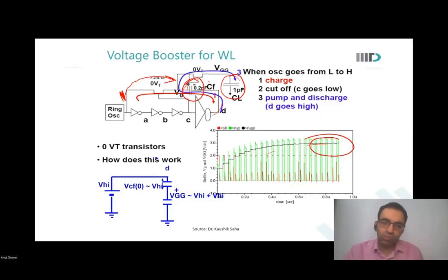So, have you tried equalizing two signals, bitline and bitline bar, when you are precharging them in the SRAM itself? Let us say, forget about the DRAM. In the SRAM, there is a bitline and bitline bar, and you want to equalize them. You put an equalizer there. How long does it take, do you think? Don't know, but I think the bit line C is very high. That's why it is taking too much time? Yeah, that is definitely there.